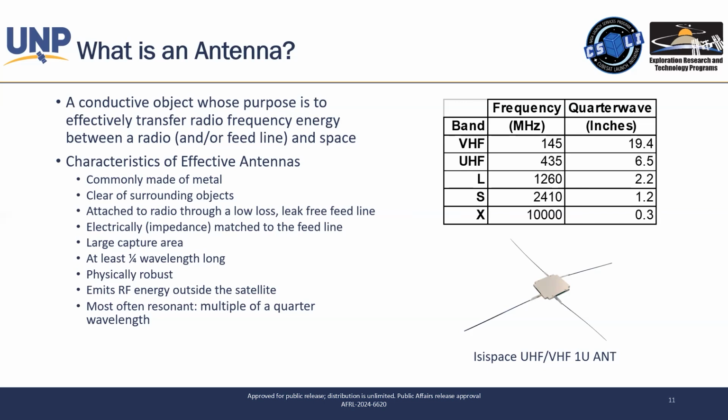You'll have antennas that they'll tout all sorts of gain figures and they'll be amazing, but you're like, how on earth are you supposed to get that aboard a satellite? Some of them are impossible to get aboard a satellite unless you had a really big satellite. With small sats, you're probably never going to get a dish on a satellite unless it's some sort of deployable. But there are different deployables, such as whips, that are more practical. In fact, they sell them commercially, and they're just these whip antennas that kind of look like a turnstile on top of your satellite. That's a deployable that has worked in the past.